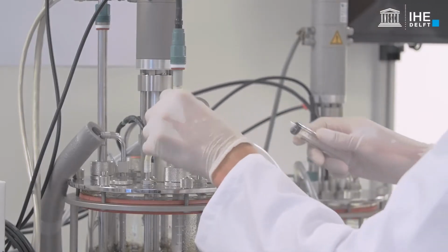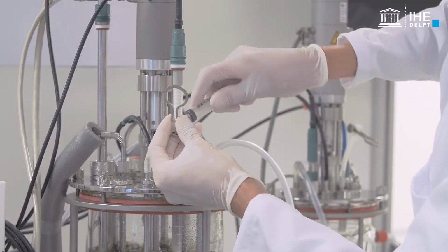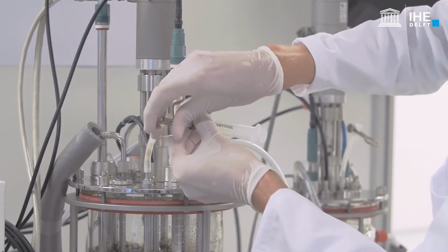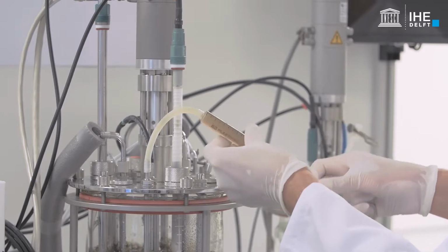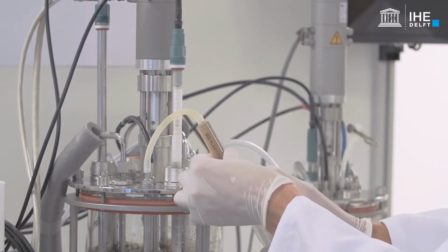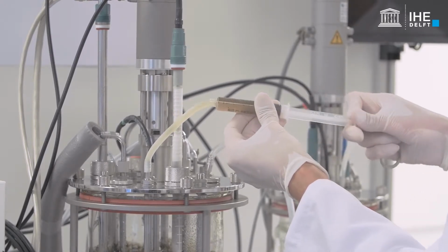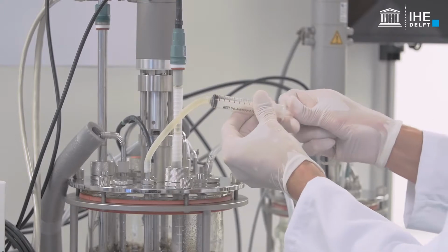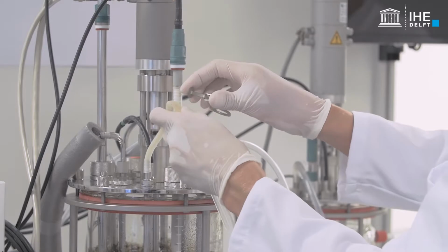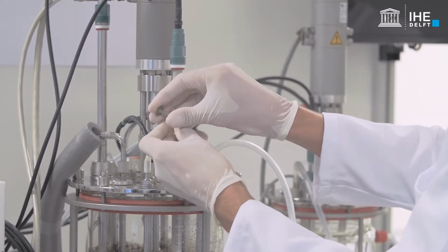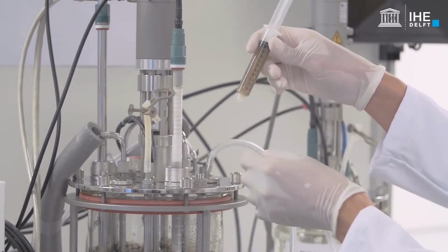Once the samples for particulate compounds are taken, continue to take a filtered sample for the analysis of soluble parameters. This is also the last preliminary sample of the test. Apply the same sampling procedure. Take the required volume for the analysis of the parameters of interest, which usually comprise soluble COD, acetate, orthophosphate, and ammonium.